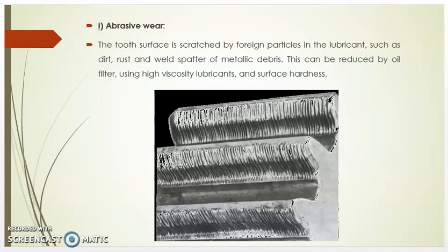First is abrasive wear. Now this diagram shows the severe abrasive wear of the gear teeth. See that. The tooth surface is scratched by foreign particles in the lubricant such as dirt, rust and weld spatter or metallic debris. This can be reduced by oil filter, using high viscosity lubricants and surface hardness.